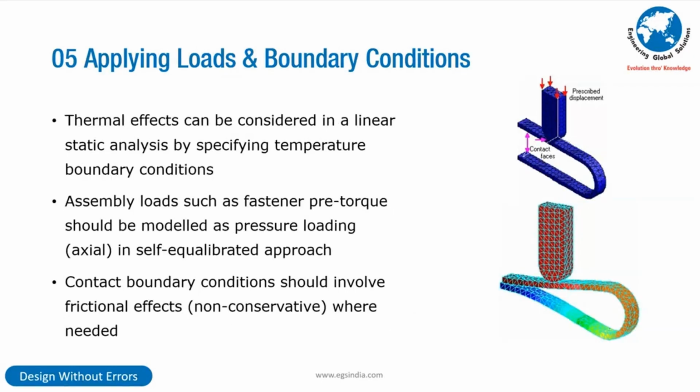Thermal effects can be considered in the linear static by superposition. Assembly preload torques need to be brought in with a self-equilibrated approach. The contact boundary condition should involve frictional effects, as I told you earlier. There's an example shown over there with the self-contact.